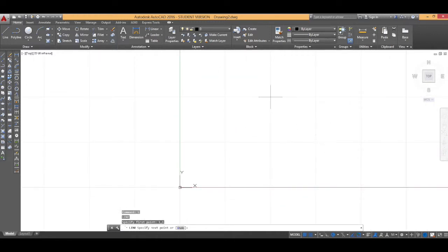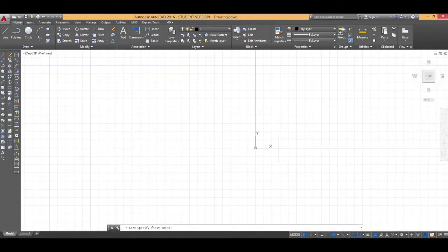As you can see, according to this grid, each line on the grid represents ½ inch, and it's placed us directly on 1 x and 1 y. Real quick, I'm going to turn off my snap settings for the grid. While some people work well with polar coordinate system, we will use another input method.